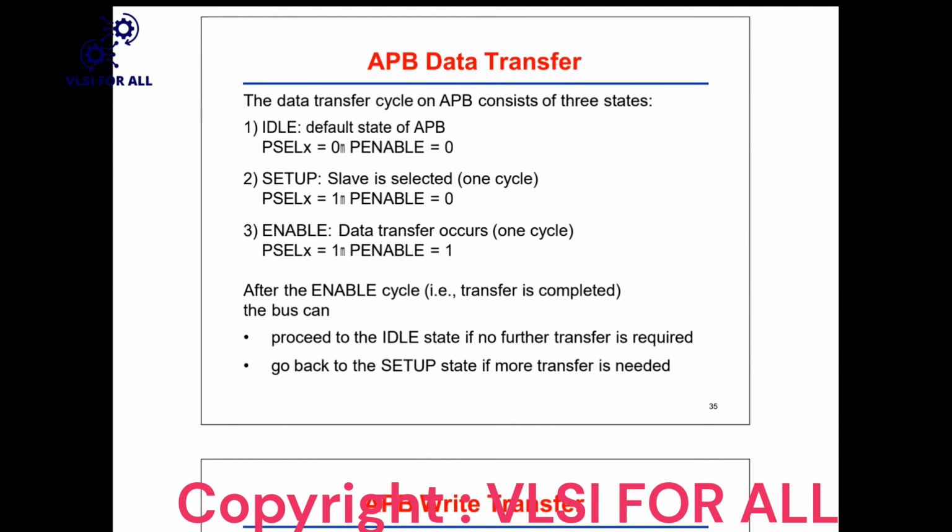Yes, sir. And if you have to complete 10 transactions, after access you will require 20 clock cycles overall to complete your 10 transactions, and after that no transactions are left. Then again you will move to the idle state. In the idle state, PSELECT will be 0 and PENABLE will be 0. This process will keep going like that. You can imagine it as a state diagram: basically idle, setup and access.